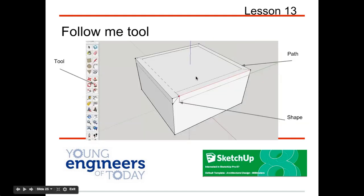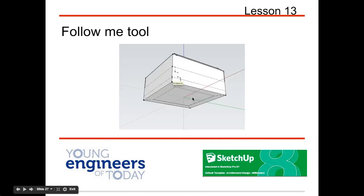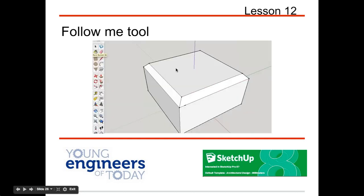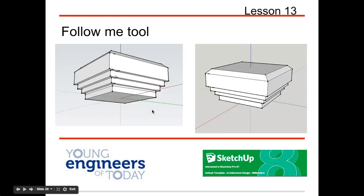In this case, I initially drew this rectangle, and in order to get the circle to bisect it, to cut it in half in that flat direction, I pressed my Shift key, made this circle down below, and while still pressing that same Shift key, I could orient the circle this way. We used the Follow Me tool, which needs that shape and the path. That tool is right there, and you can use it to cut away and to add to objects. This was really cool because you could see that with a simple shape such as these stair steps, you can create a really cool, larger 3D shape.